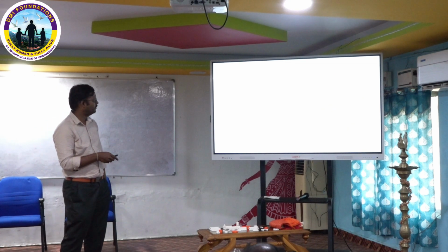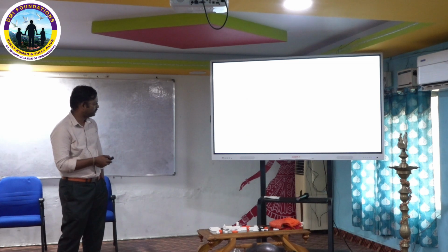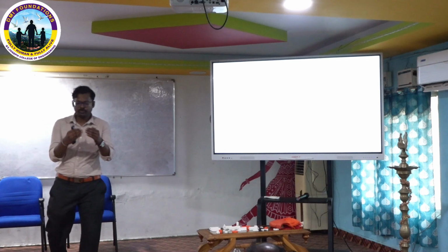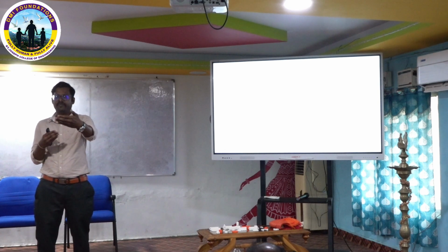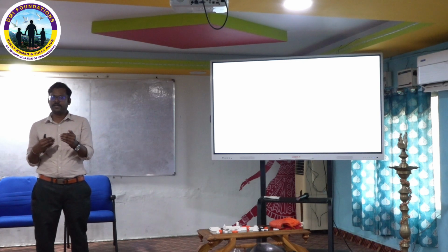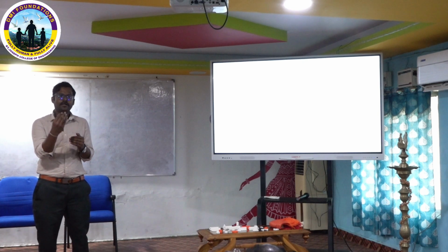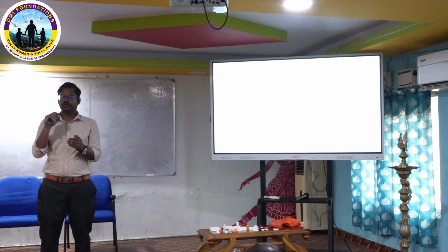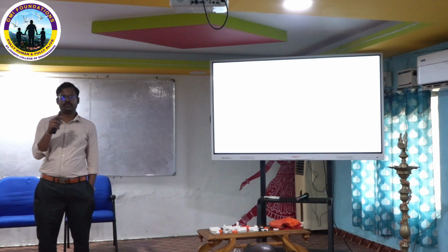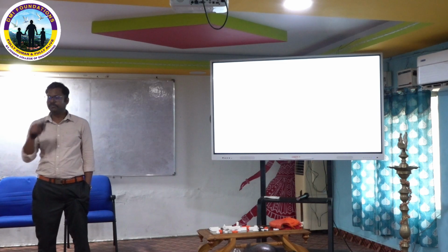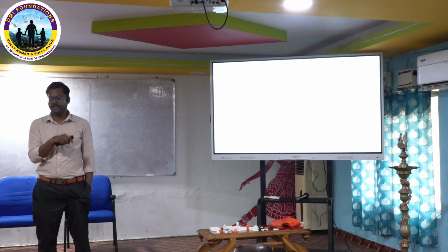Also, when we compare the natural frequency or damping ratio with relative density, 10 to 20%, when relative density gets increased, the natural frequency gets decreased. Actually, the equation for natural frequency is omega equal to root of k by m. What does it mean? If mass m gets increased, the natural frequency should decrease.